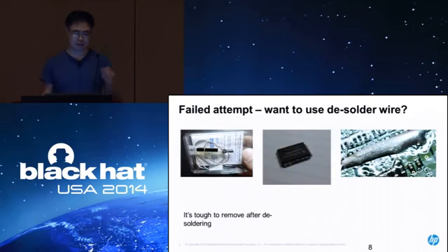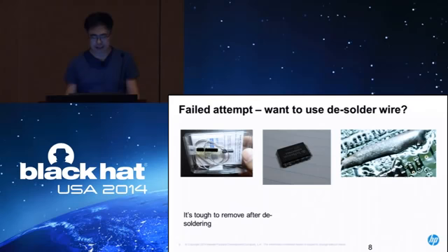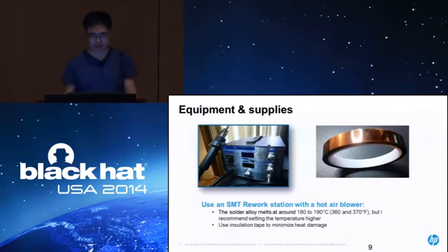And the other option is desoldering the chip using ChipQuick. I tried this on other types of chips, but this one makes the chips really messy, and the PCB board is filled with all the remaining solder fluid or whatever. So I didn't really like it, but other guys use this a lot, I guess, but I didn't like this option.